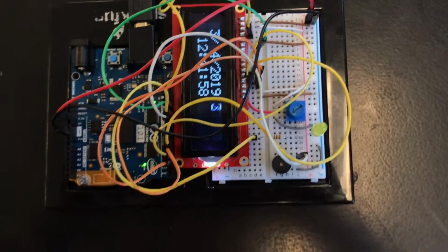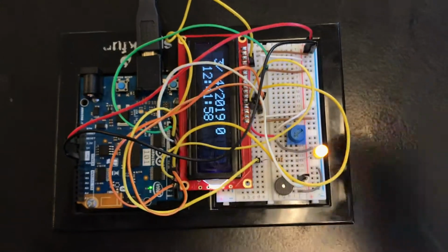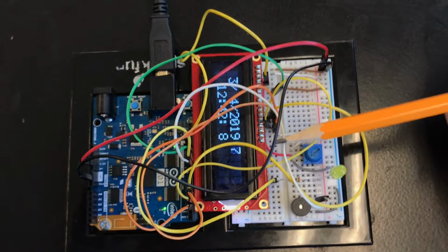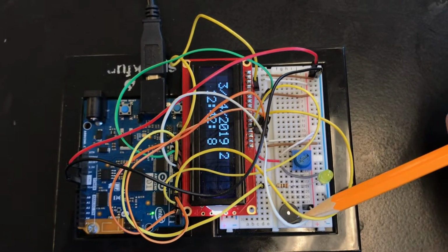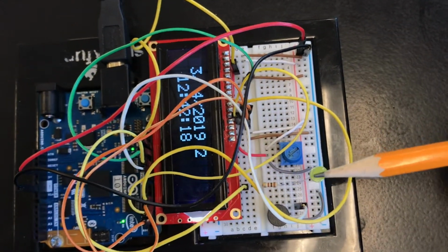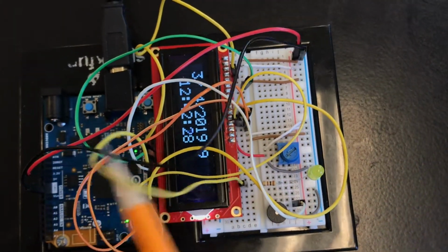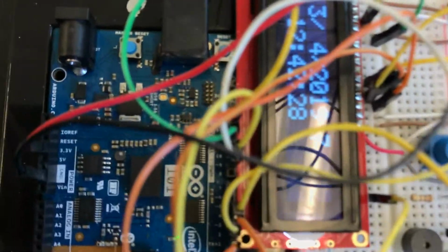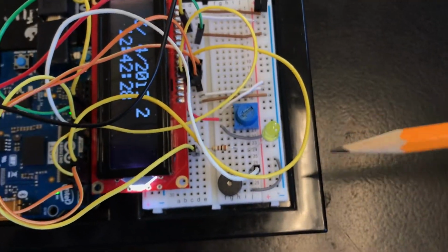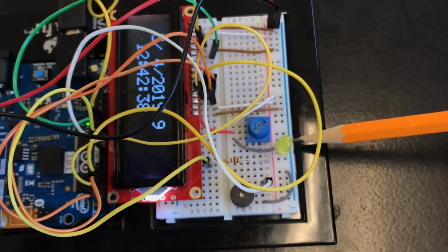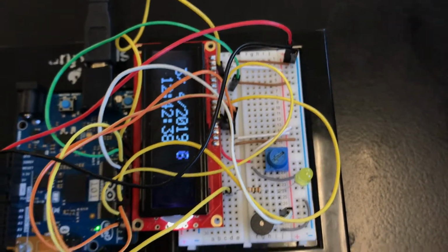Here's the modified board for using the onboard time clock. Here we have the LCD screen wired the same way as before. We've just moved up the potentiometer to leave more space for the LED and the piezo buzzer, and we've switched the wiring so it leaves pin 11 open. When we get to the LED here, it is connected to pin number 10 through this yellow wire on the Arduino, and it goes through a 100 ohm resistor to the anode of the LED, and then it is grounded by its cathode by connecting into this negative column here, and then grounded by this black wire.